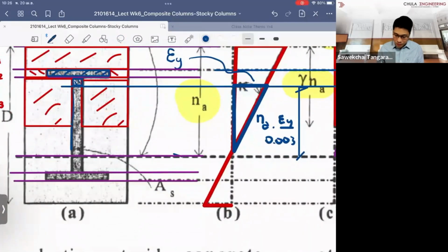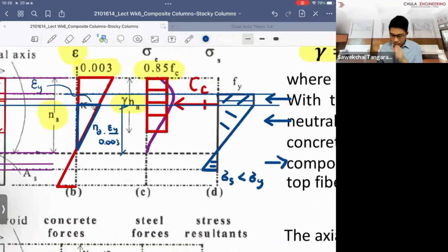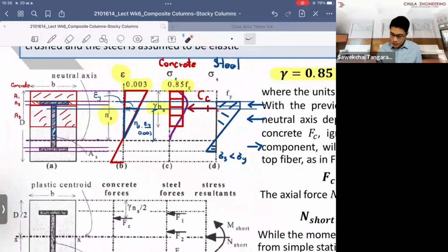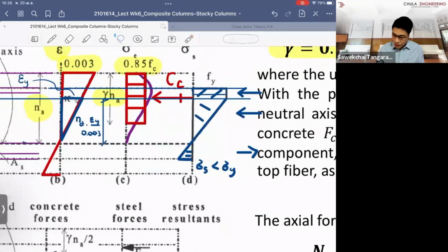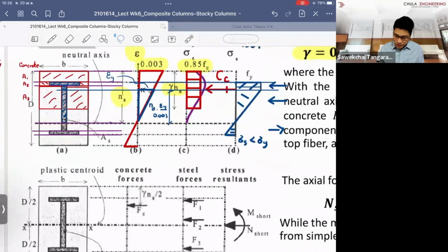And once it happens at the bottom here, it now develops the stress according to the triangle areas. So you have to find the triangle stress times the areas here. Okay, we need to factor in the thickness of the web part. And similarly, you do for the bottom to get the tensile force. So that's why you have so many forces in the steel.